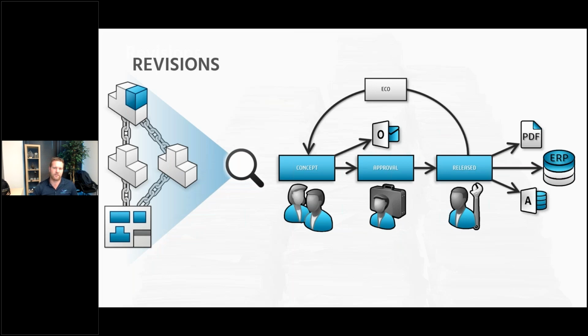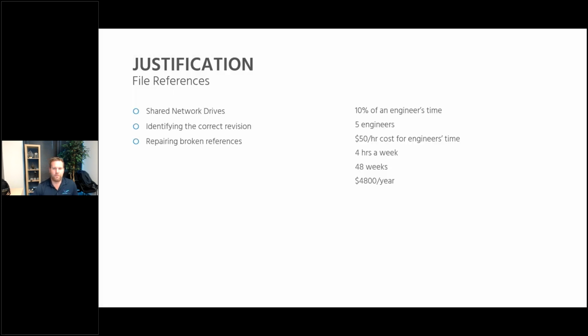We do have an engineering change request. As long as the user has permission, they can instantiate an engineering change process: just right click on that file and send it back to concept. It'll automatically increment that revision variable, another use case for automation, so we don't need to worry about managing it or ever being concerned about it being out of date. It moves back into that concept state so that the engineering change request can start getting that work done to it.